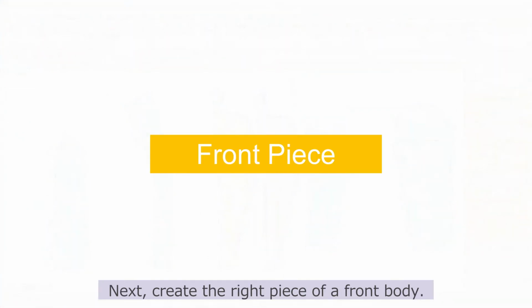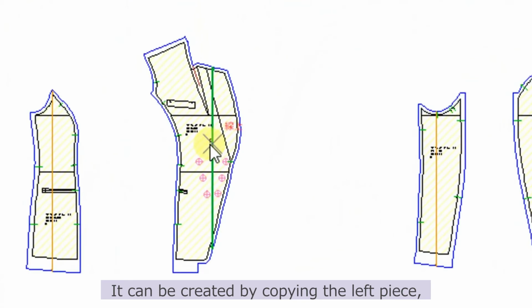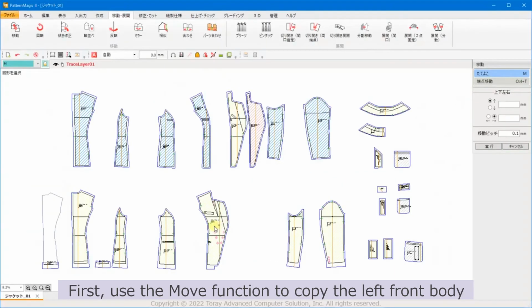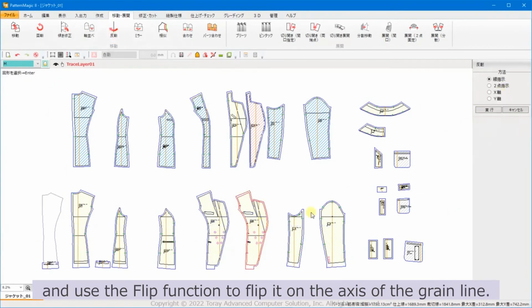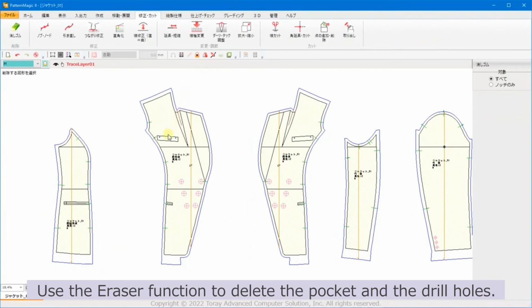Next, create the right piece of a front body. It can be created by copying the left piece, but if only the left front has the pocket, you need to delete it and the drill hole from the right piece. First, use the Move function to copy the left front body and use the Flip function to flip it on the axis of the grain line. Enlarge and check the front body. Use the Eraser function to delete the pocket and the drill holes.